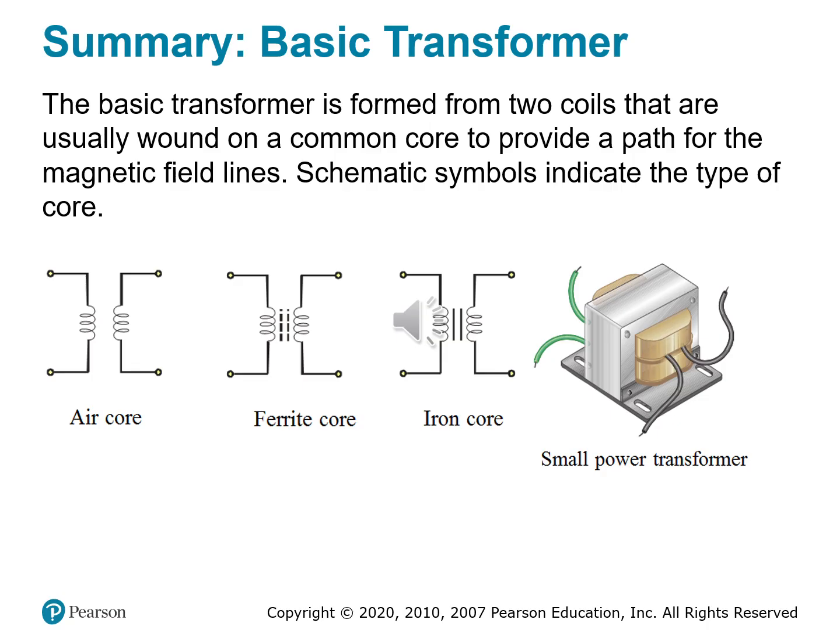Then we have the ferrite core transformer. It uses a ferrite ceramic-based core. This is excellent for high frequency circuits like switch mode power supplies and RF transformers, or radio frequency transformers. You have low losses at high frequency.